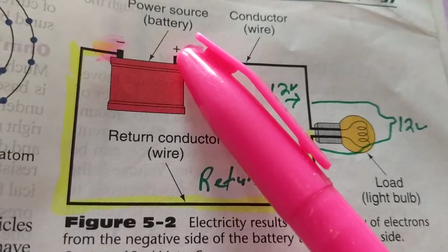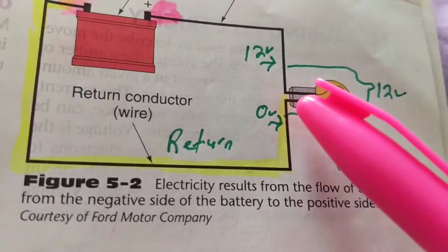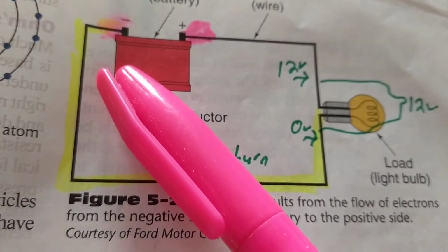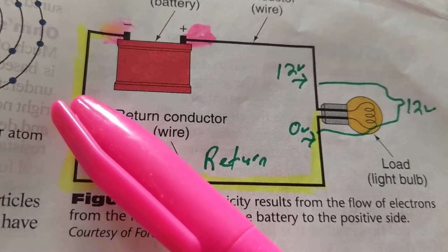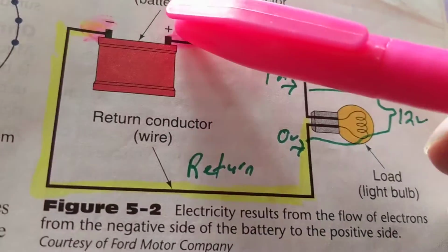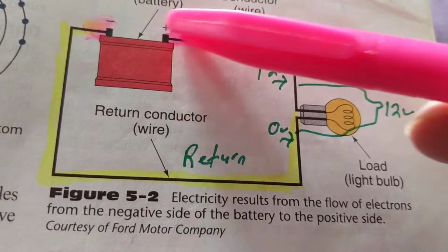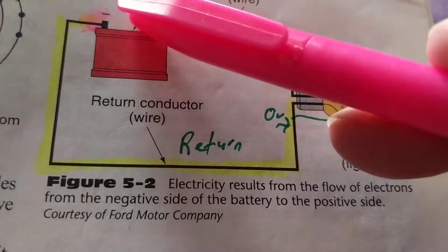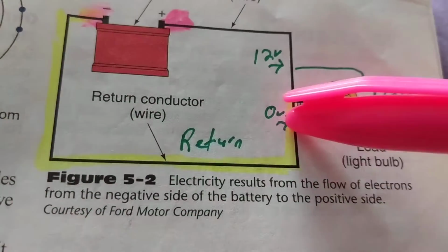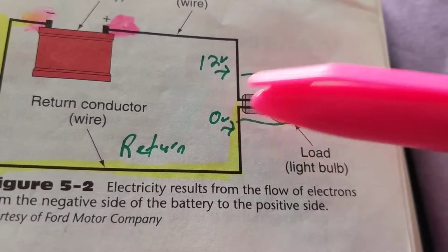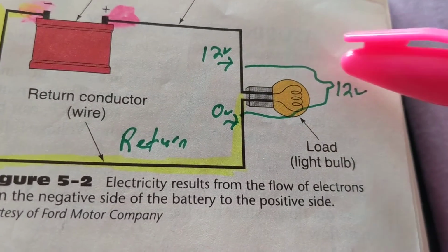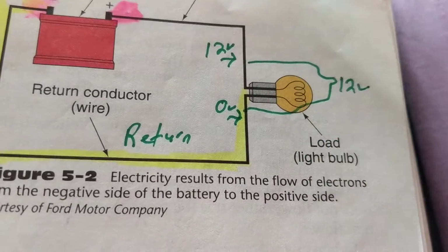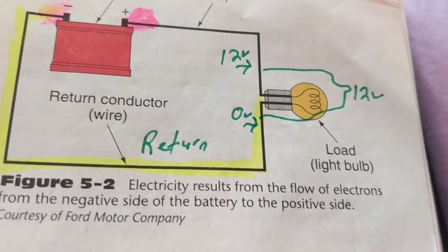Plus a connection from here to here through a wire, through one side, and then the other side back to the negative. This is our ground return line. Now, from that, we know we have 12 volts over here because we do not lose any voltage through this wire. The other side of it is connected to ground, which means it's 0 volts over here. How much is the total across here? If there's 0 here, there's 12 here, we lose the whole 12 volts from the battery across this lamp or fuel pump or anything for that reason.